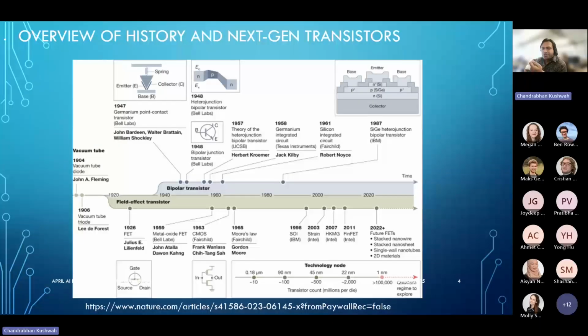So earlier efforts to manage these effects focused on physical scaling, the gate oxide layer, and tuning the doping profile in the transistors' source, drain, and channel regions. But in the 21st century, attention has shifted to advanced materials and novel structures as well, such as strained silicon channel, high-K metal gate, silicon on insulator platforms. And the very interesting one is FinFET architectures to address the scaling challenges. So all these solutions came into the picture around the 21st century, so that we can cope with the scaling challenges.